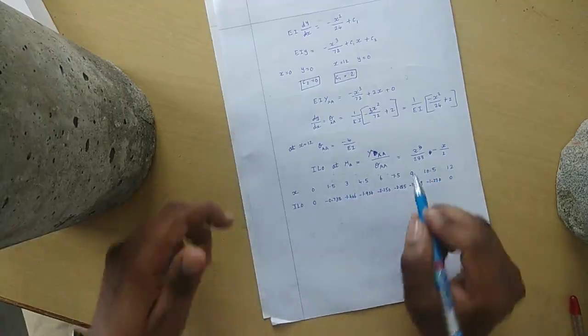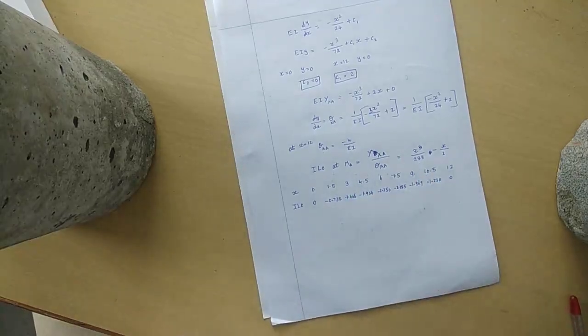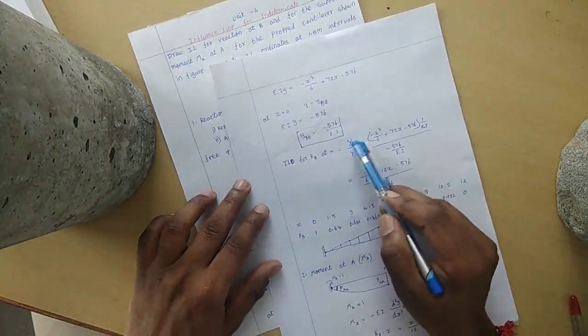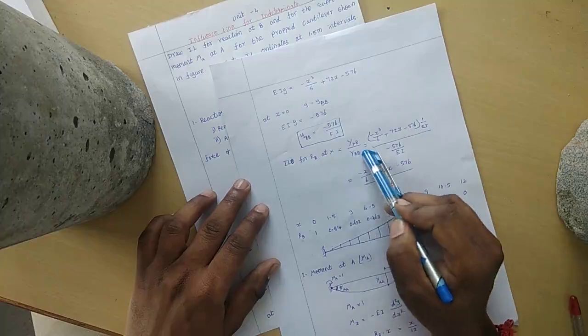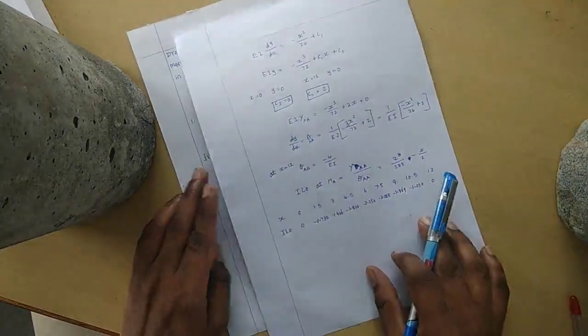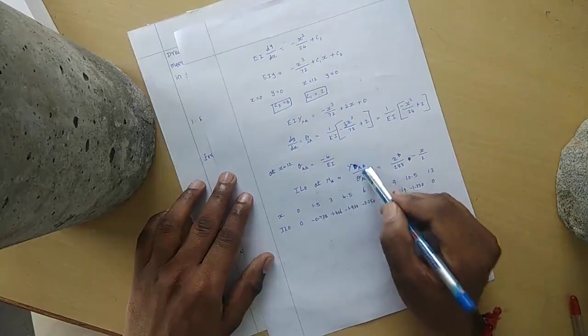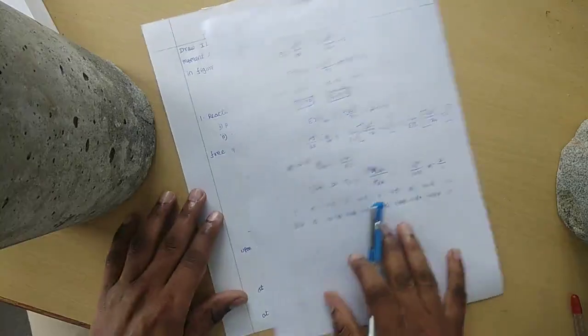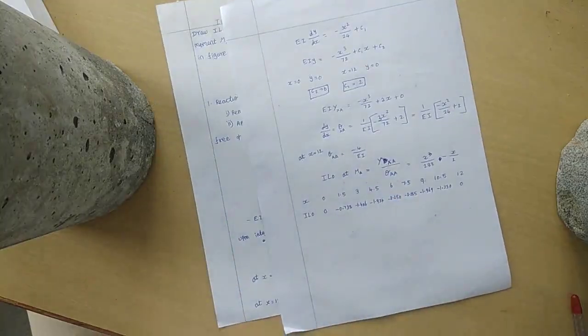If we want to calculate the reaction, then we need to consider the y value, that is deflection at the point required and at the x distance, and compare the value, that is yxb divided by ybb, because at ybb only we need to calculate. Here in the second condition we need to calculate the moment. So we have taken the deflection at yxa, and for the moment we are going to apply a rotation, so we are considering theta AA. Remember this: if we want the force, then we need to use displacement by displacement, that is displacement at x distance by displacement at the required point. If you want the moment, then we use displacement at x distance divided by slope at the required point.